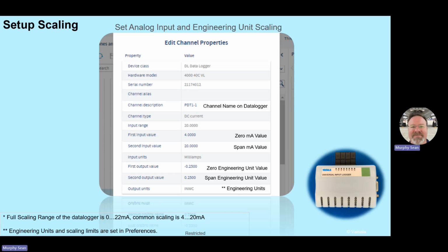So once you configure this, before you can actually get this to work properly, you need to make sure that you have those engineering units as units in viewLinc first. Otherwise, you're going to run into problems when you try and create locations for device units that don't exist inside of viewLinc. You have to configure that, and that's under preferences. So as long as you have the units existing inside of the viewLinc system, you should have no problems with the labeling.